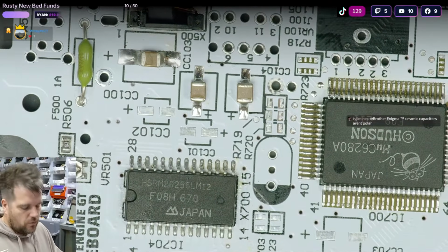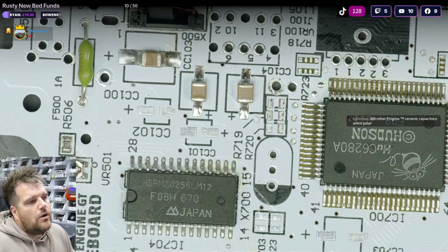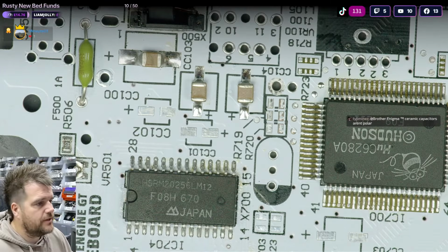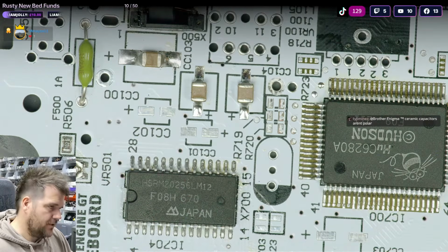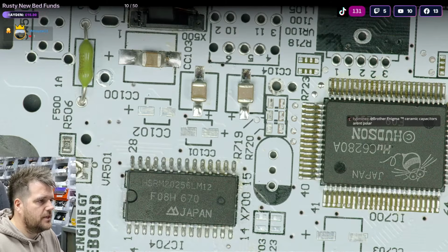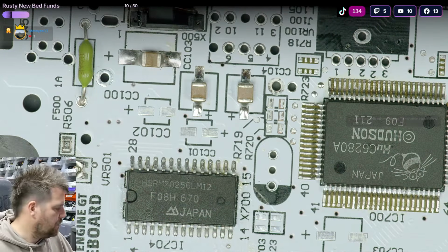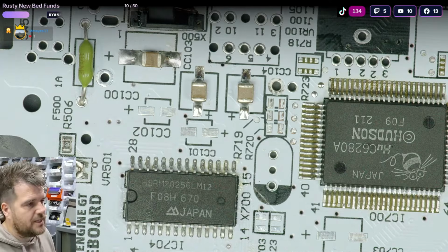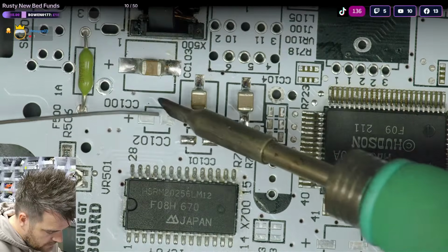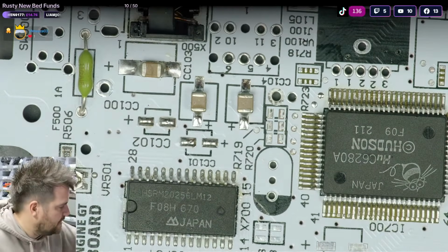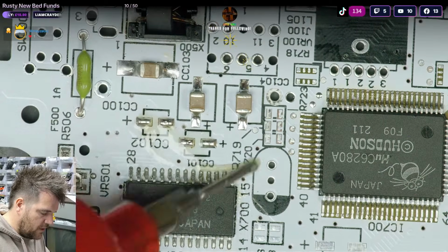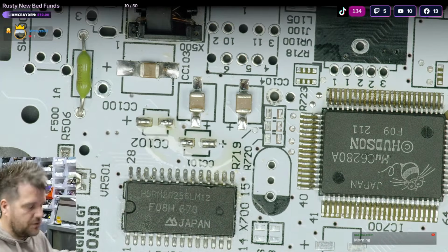Right, CC101 and 102 are 33 microfarad. So these can be 47 uprated because 33 in aluminiums, it's not going to be anything specific on the filtering. This is going to be more of a stability cap, a bulk cap if you will, and ceramics tend to be a little bit down rated on the capacity versus aluminiums. So when you're redoing the circuit with ceramics, sometimes depending on where they're used, you want to slightly uprate them, and 33s are not that common anymore. I rarely see a circuit in modern tech that uses 33.